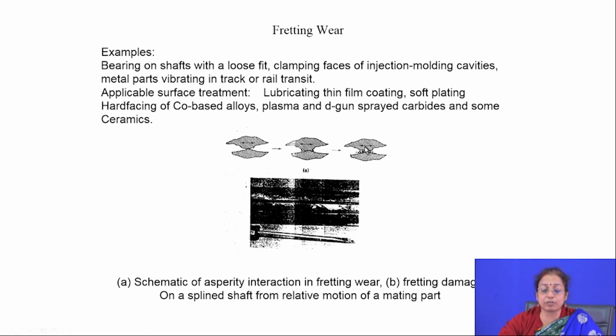In all adhesive wear, the mechanism of wear changes from 2 body to 3 body at a later stage of wear, and the kinetics of wear is very much dependent on the kind of loose particles that are formed because of the adhesive interaction.